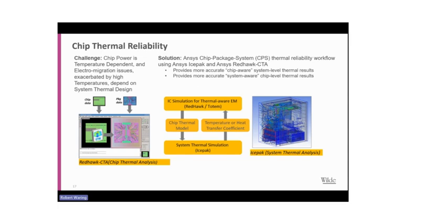With ANSYS RedHawk, you can analyze the temperature gradients and thermal cycling effects within the chip. You can predict and mitigate the risks of electromigration due to elevated chip temperatures, and you can optimize the cooling strategies and hope to maintain the temperature of the chip within safe operating limits.